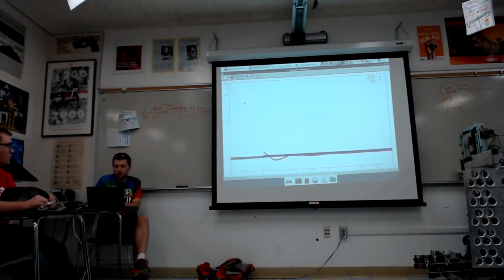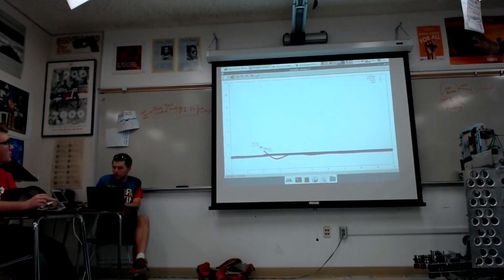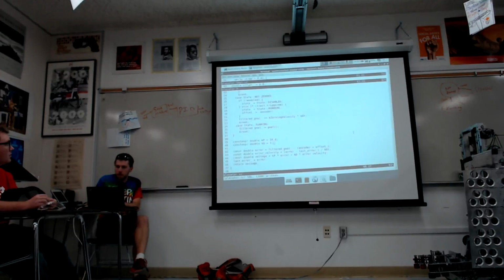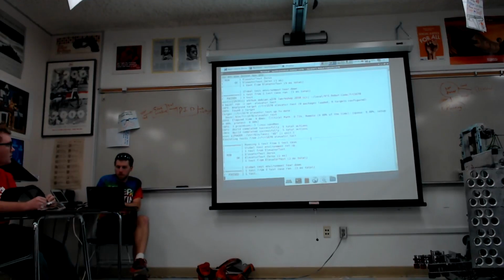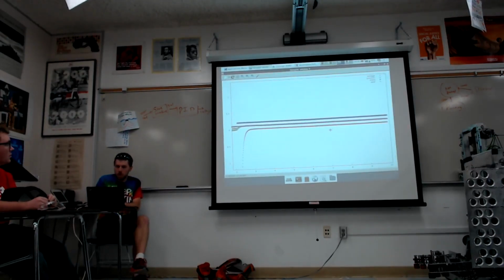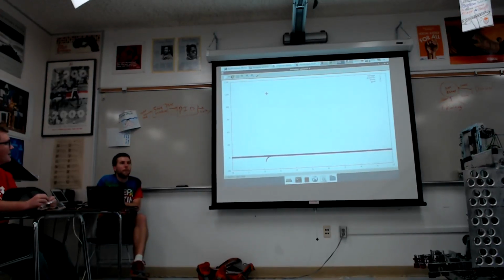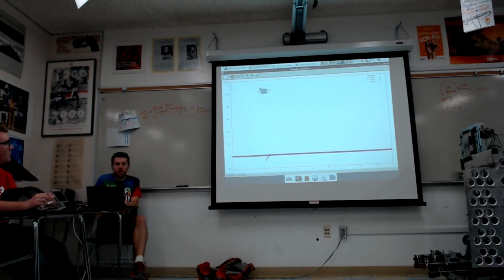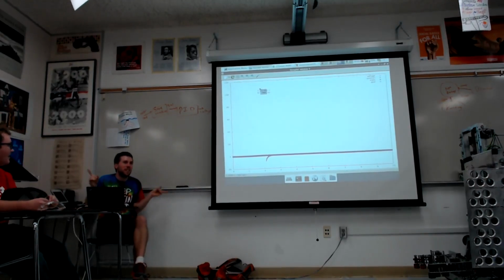We're starting to settle up. Actually, though, we have this interesting artifact here. We should figure that one out at some point. There we go. I think we should find this one. The robot all of a sudden asks for 100 volts. So there's two things wrong with that. First of all, is 100 volts possible? No. So that's a bug, which actually means we should write a test case to catch it.